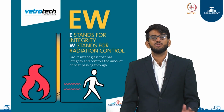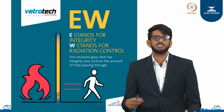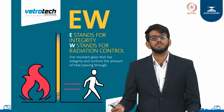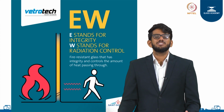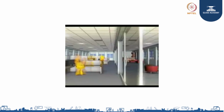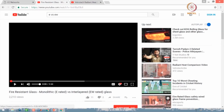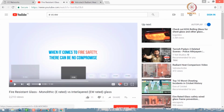On the other hand, an EW-rated glass has both integrity, which is the most basic property of all fire resistant glass, and in addition, something called W, which stands for radiation control, which means that it will control the amount of heat passing through the glass. Now, I will take you through some videos which will show you the advantages of using an EW glass.